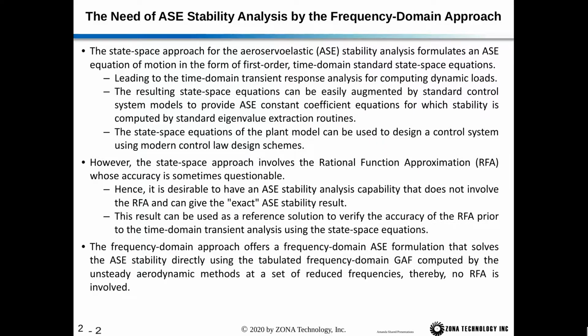The state space approach for the aeroservoelastic stability analysis formulates the ASE equation of motion in the form of first-order time domain standard state space equations. Now the advantage of this is it leads to the time domain transient response analysis for computing the dynamic loads, and these state space equations can easily be augmented by the standard control system models to provide the ASE constant coefficient equations for which the stability is computed by the standard eigenvalue extraction routines.